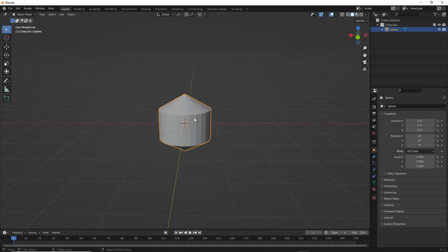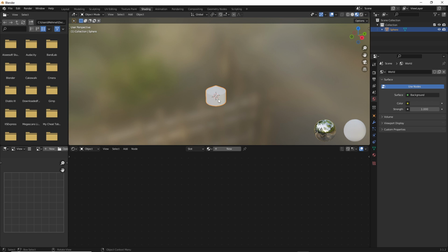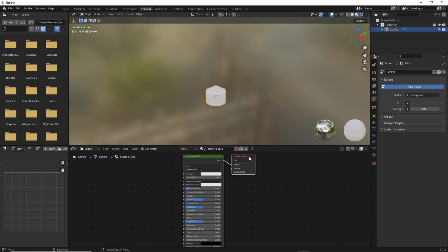But we are going to shade. Let's repeat the shading step. First of all, we go to shading. Our object is selected and we click here New. Okay, and then we bring a texture in, a PNG image actually, which I had last time, and in this image I had saved some colors.